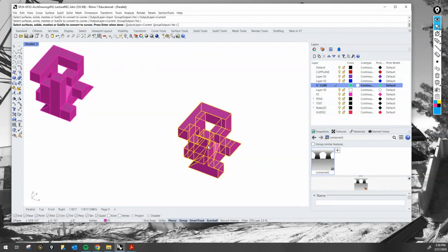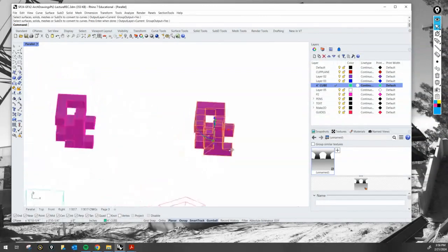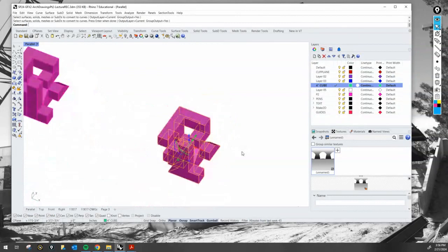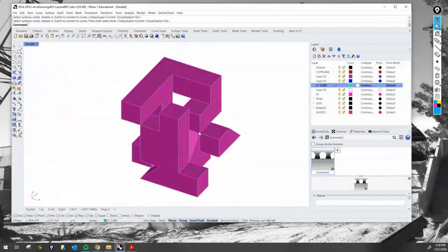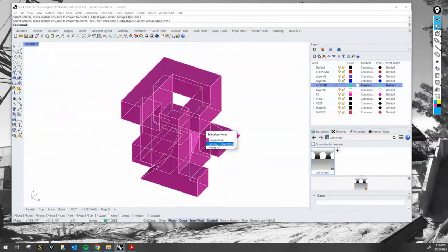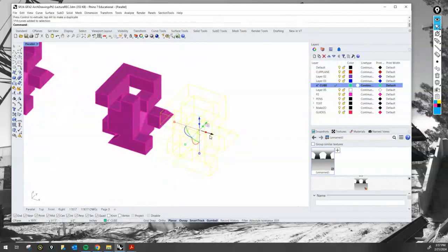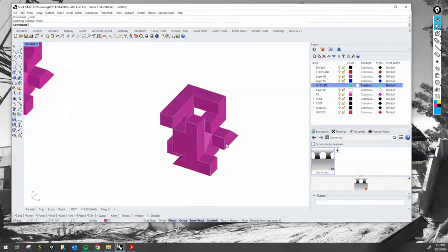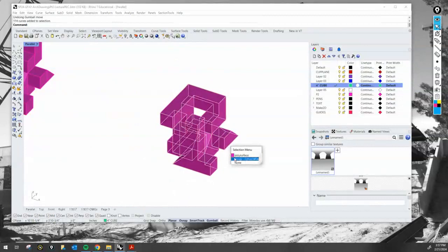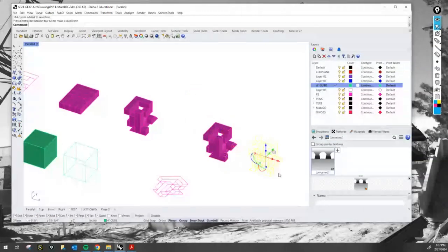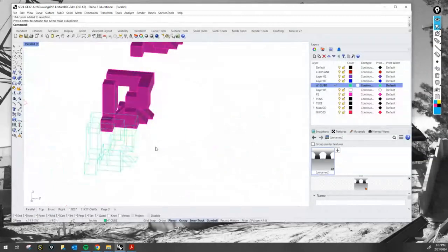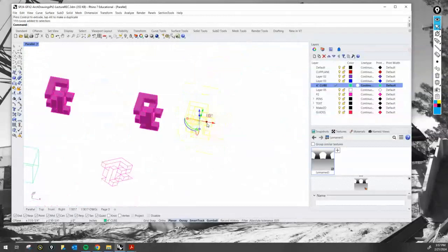Let's see what we get. I'll select that object, enter. Notice that if I click out, the lines stay there. But since they're grouped, the good thing is that I can click on it, and I can either select the poly object, or I can select, I'm going to undo, or I can select the extracted wireframe, which is a group. It says extract wireframe, so I'm going to select that, move it out here, and you see how well we ended up with that. Whoops, we don't want that.